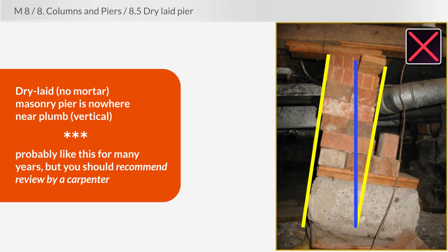And I'm sure at the time they set it all up, it was pretty well vertical. But over time, it's shifted. It's nowhere near plumb. This really isn't that big of a deal, truthfully. Obviously, you want to report it. It looks terrible in the picture, but you'll just recommend review by a carpenter.